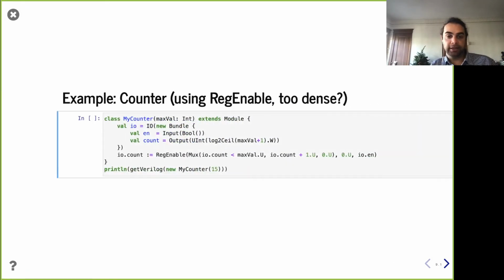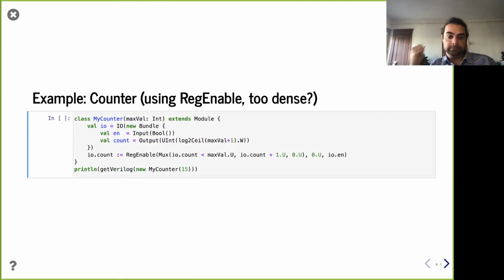Cool. Yeah, good questions. Just a moment ago, you heard me talking about, hey, what if I wanted to use reg enable? Well, if I verbosely reuse a circular reference to myself, I can, and I jam a mux in there for next val. Remember, the problem I had previously was I couldn't write the next val line because I needed a reference to count. Well, if I do that internally, I can.